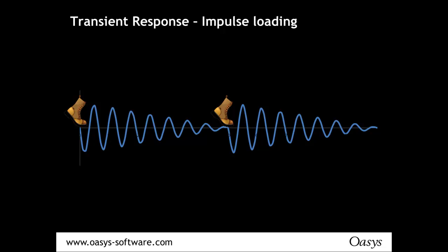So damping values actually have no impact on transient responses. It's all about that initial peak value, and you need to basically check both. A lot of it depends, and you might find that in certain parts of the structure resonance governs, and in other parts transients govern.